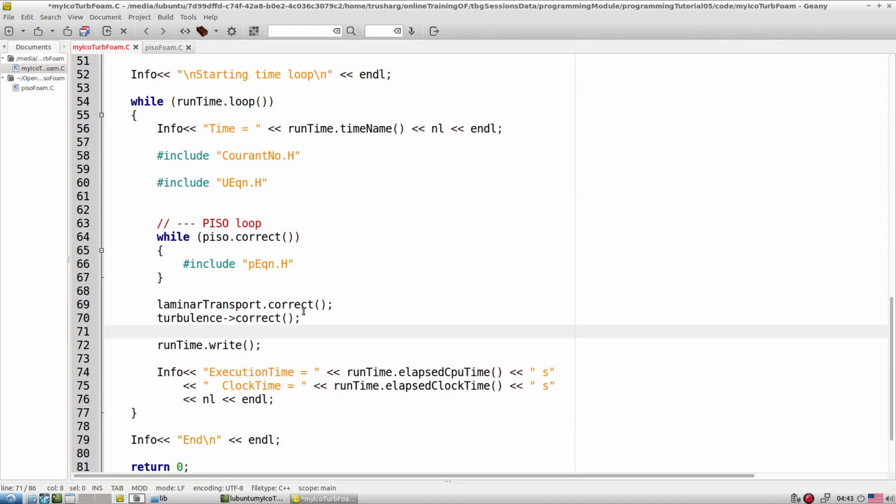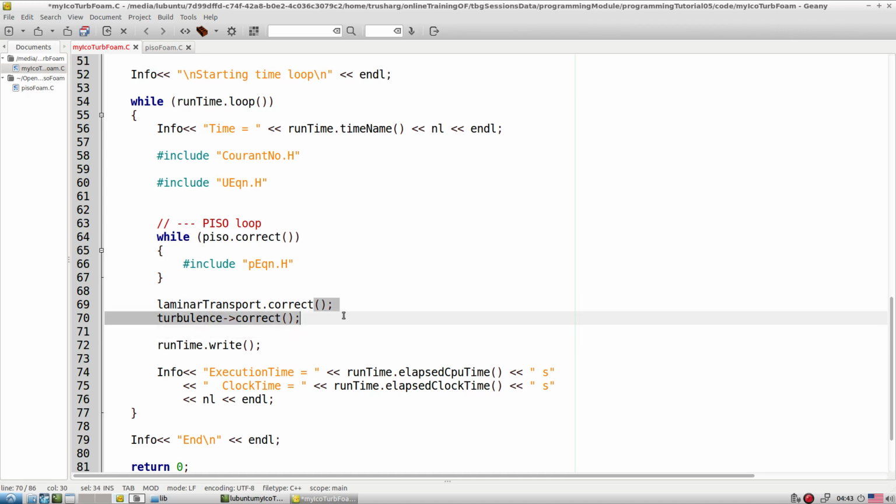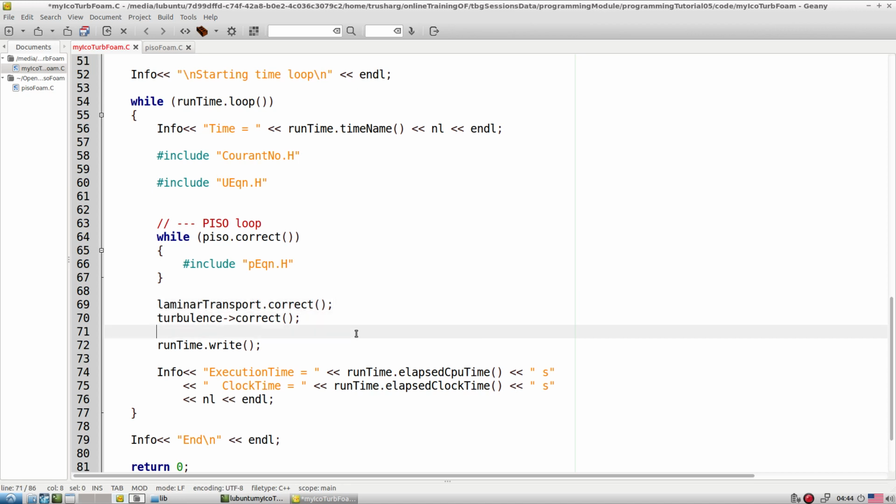Along with that, what different change? So this turbulence corrector, what is it going to do? It tries to solve depending on our selected turbulence model. It tries to solve the turbulence model with this entry. Okay, so it directs the solver to the particular library. If we are working with the k epsilon model, it is going to use the k epsilon model, or k omega.